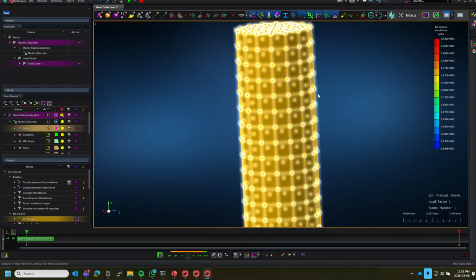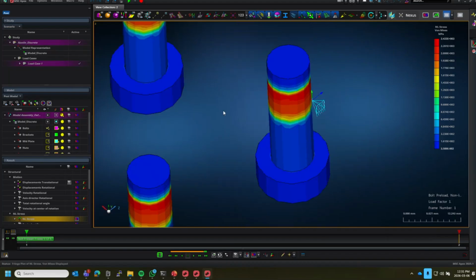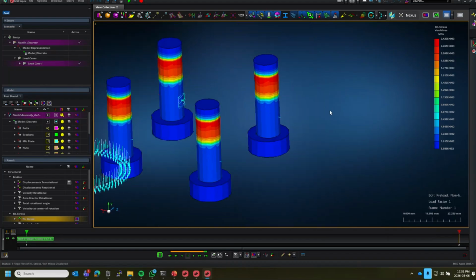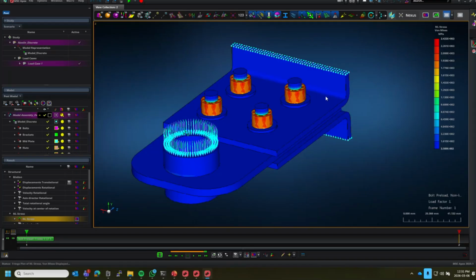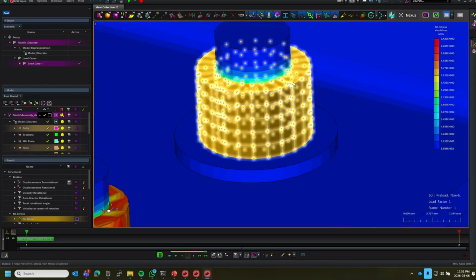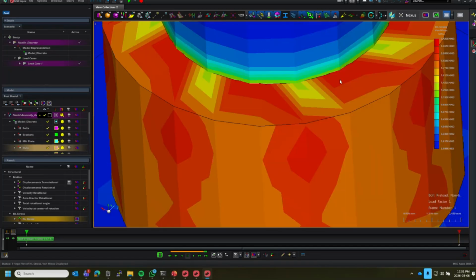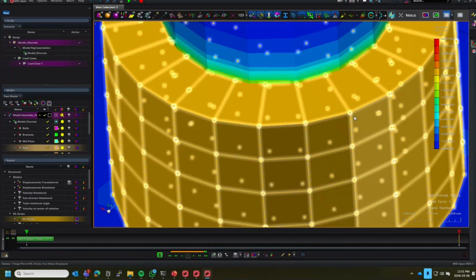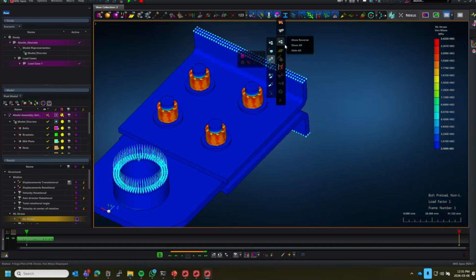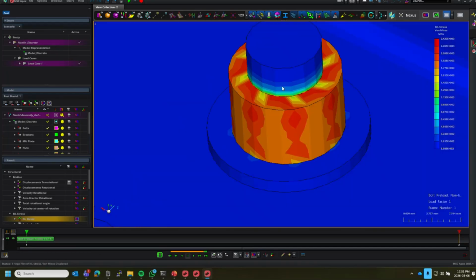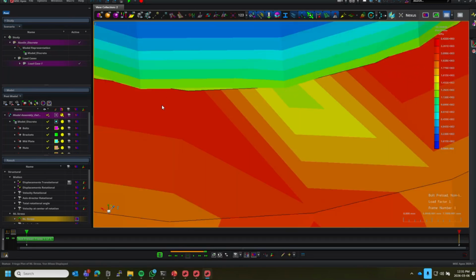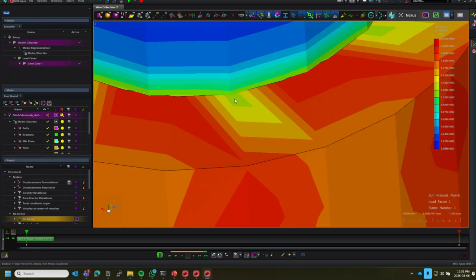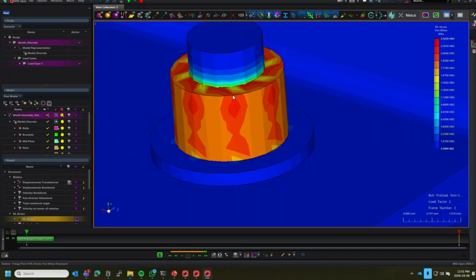And that's simply because some spots overlap and some not and so on. So you end up with really strange results in that location. Now, the way that I've recognized it immediately on seeing this is if you see these kinds of spikes, but you expect it to be smooth, that's a giveaway. There's a high stress and then almost zero stress in that location. Okay, so that means, and if you zoom in, you'll see, oh, there's overlap, high stress, and there's a bit of a gap, depends on which direction I checked, so it kind of makes sense.